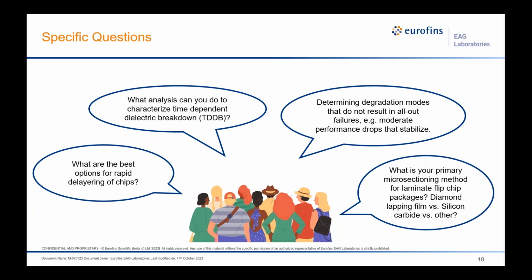defect in that area. Now, if we have a non-specific area, maybe a block of circuitry, during the deprocessing it may be difficult to maintain the uniformity and planarization that's needed to look at a larger surface area at each layer as we remove the process layers.